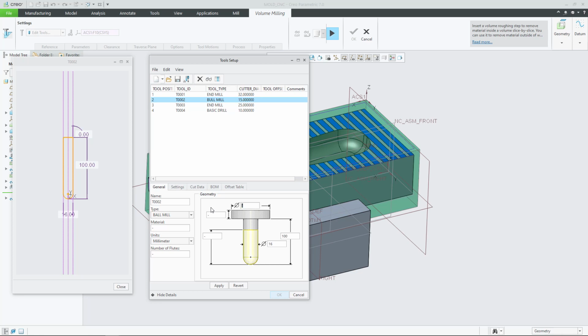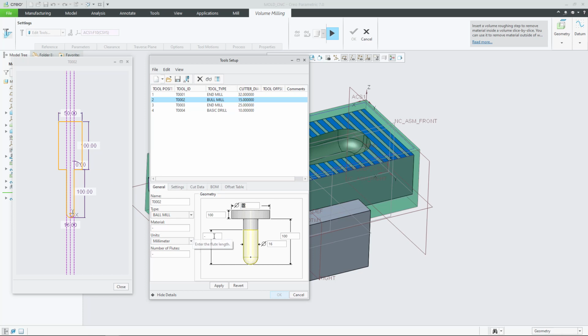So BT40 is a common type of tool holder, and we would have to get the geometry for the maximum diameter of that and the typical height from elsewhere. But that's a simple search for BT40 tool holders or similar styles of tool holders. The maximum depth of cut is 14.4 for this tool. So yeah, we filled in the tool geometry there.